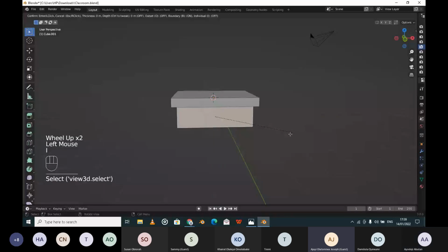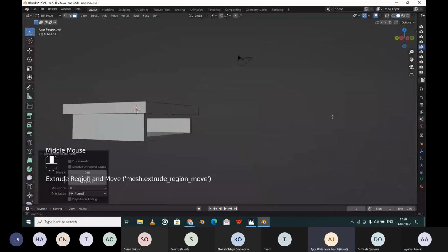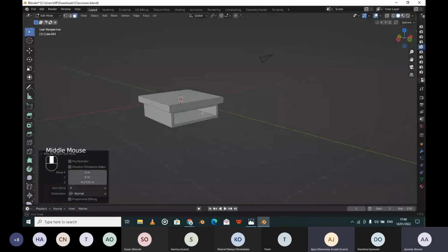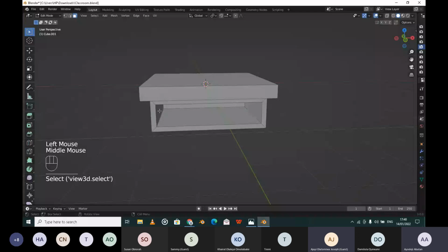Yes, I understand. Okay, thank you. You can insert and extrude inward. With insert and cut, you have to be careful so you don't extrude beyond the back of your cube. Is that clear? And this even fixes the problem we're trying to remedy in the first place, because this leaves us with some thickness inside. Do you understand that?